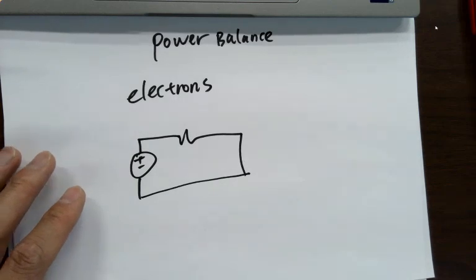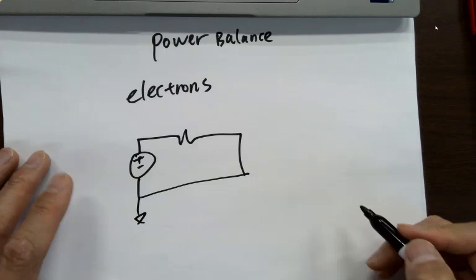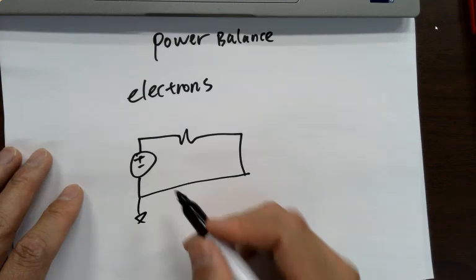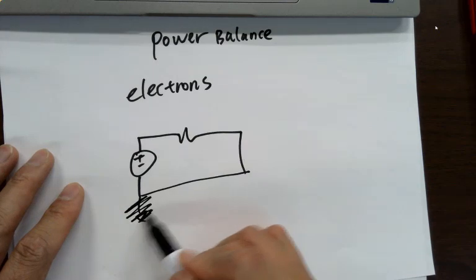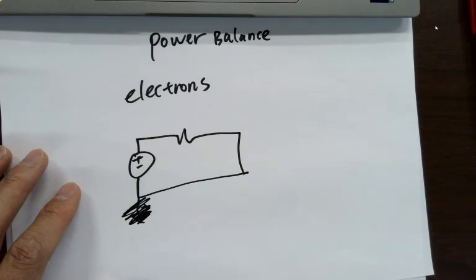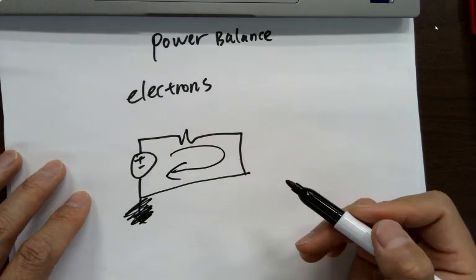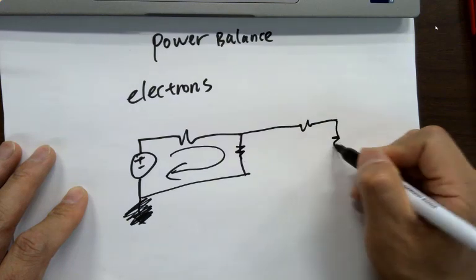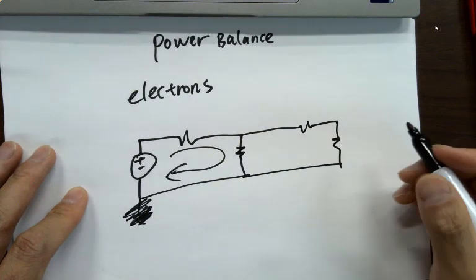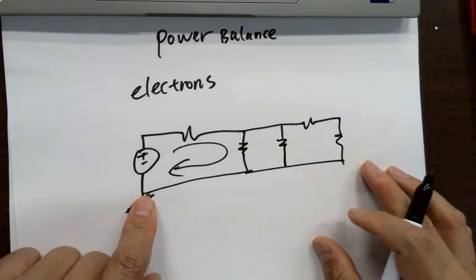You know, for a circuit, you need a ground. Using LTSpice or any other simulator, if you don't label a ground, it won't simulate. So you need a ground. You need a reference point. But if you see circuits without a ground, it's okay, because it's just in the textbook for you to calculate the currents and everything in it. Sometimes the circuit can start getting complicated. Towards the end of the semester, you'll see multiple resistors and things like that, right?